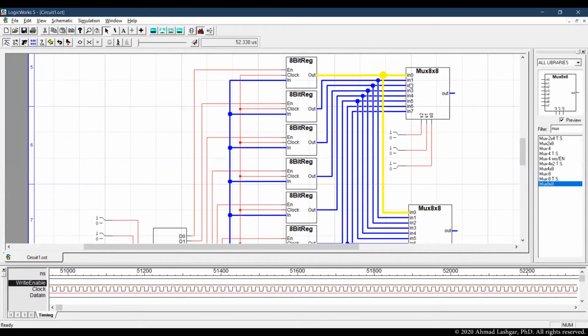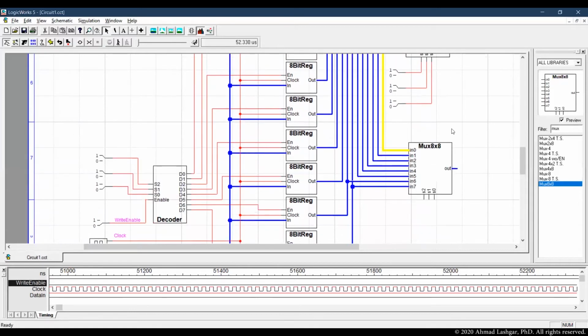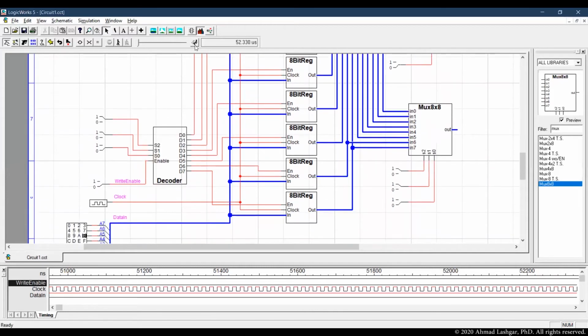Just make sure you keep the order. So if you are considering the register at the top, register 0, that should be connected to line 0 of both multiplexers. Multiplexers are identical, and they are just used for reading, being able to read 2 operands at the same time. So there is no difference between the multiplexers. Let's connect the binary switches and drivers to the multiplexer so we can test the multiplexer at the bottom too. Going to start the simulation again.